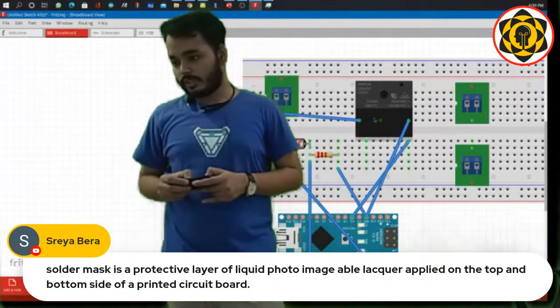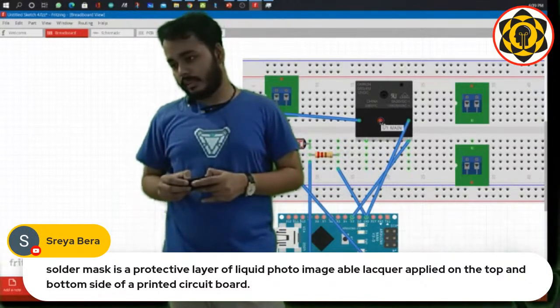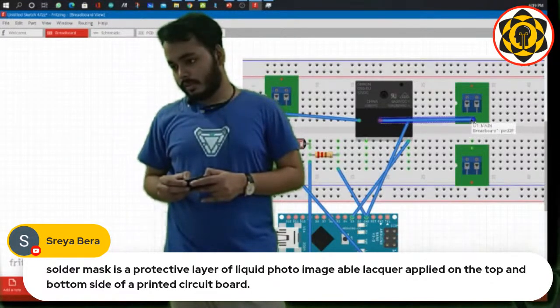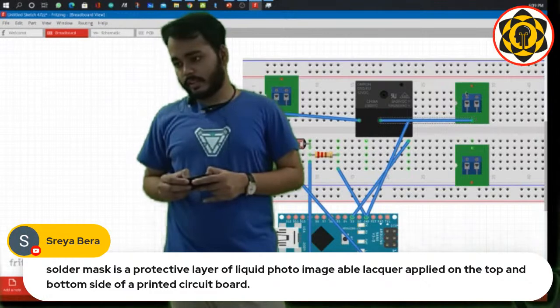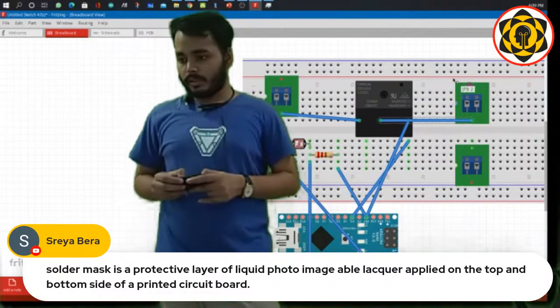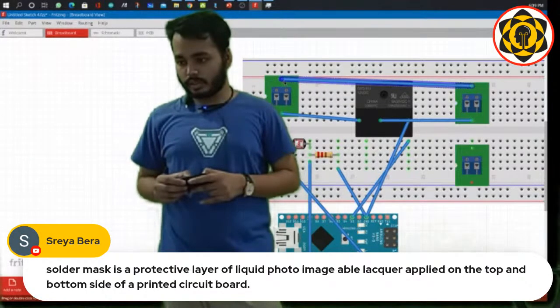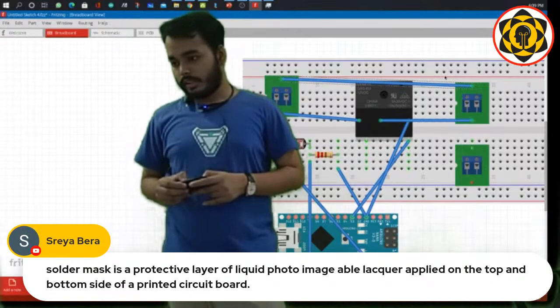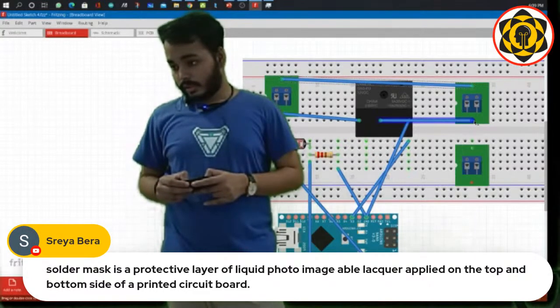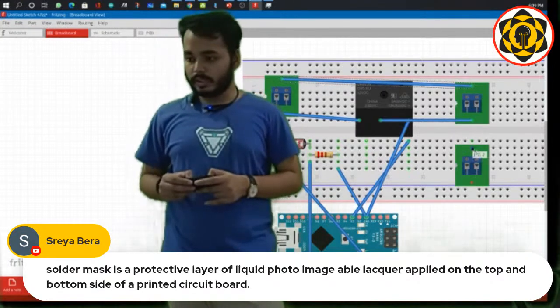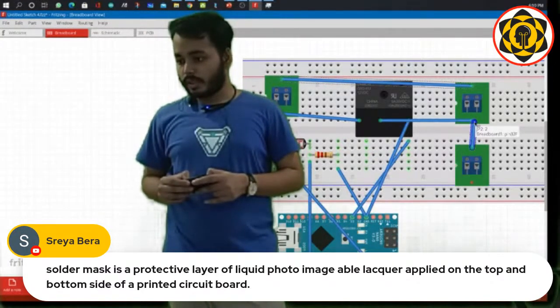So this was the switch, and then from, I guess this is the main. Yeah, that's the main. This will go to here. It's basically the place where the alternating current is entering our circuit. Okay, this will get shorted from here to here. So this is the other side of the alternating current that is going. Now we also need some current over here, because this is the place which will give power to that Arduino through that converter that I was talking about.